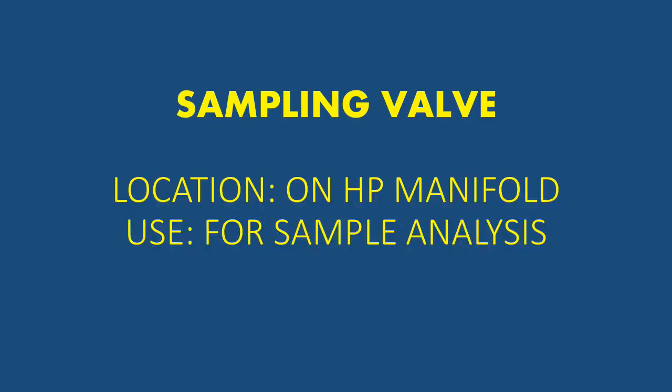There's a sampling valve also that's installed on the HP manifold. And what is that? Okay, that makes it possible to take samples of the fluid from the system for analysis. Okay, so I've talked about hydraulic fluid before and the importance of having quality hydraulic fluid and not having any contamination or any kind of corruption to the integrity of the fluid. So here's an opportunity with the sampling valve to have samples of fluid taken.